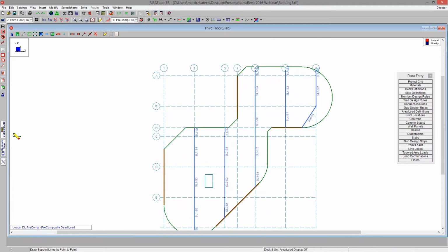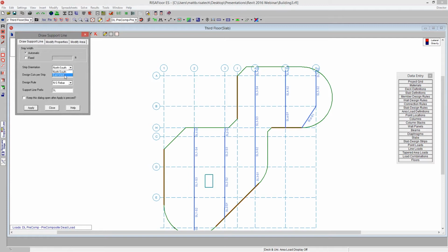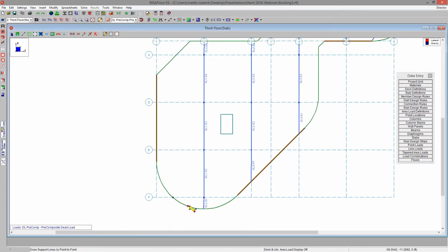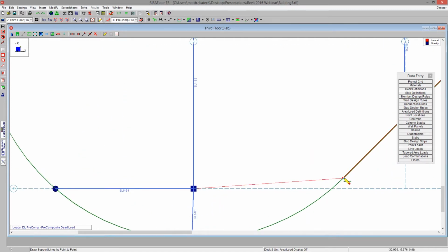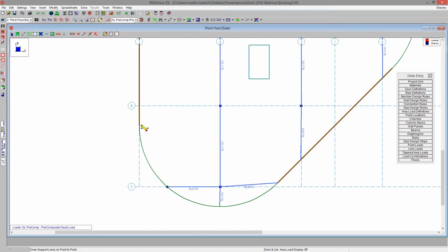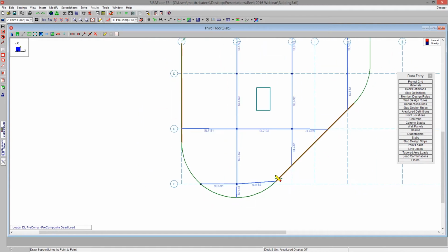So with the vertical strips now drawn, next I'm going to come in and do the horizontal ones. These would be the east-west rebar. So we'll come down here and draw the east-west rebar into the nearest supports. Right there. We can get it across between these columns and this skewed wall.